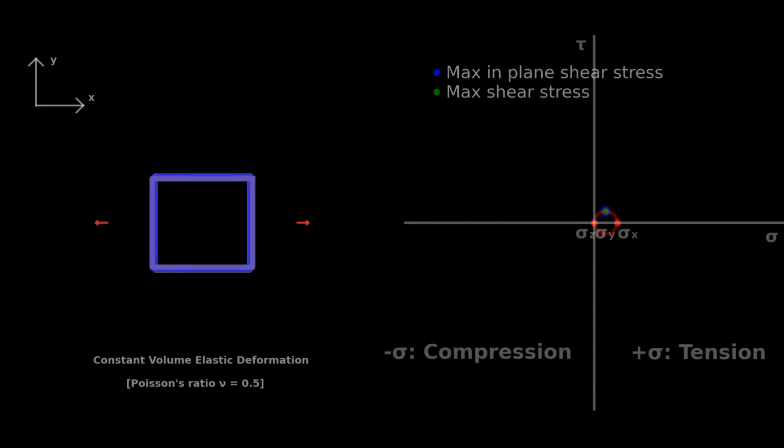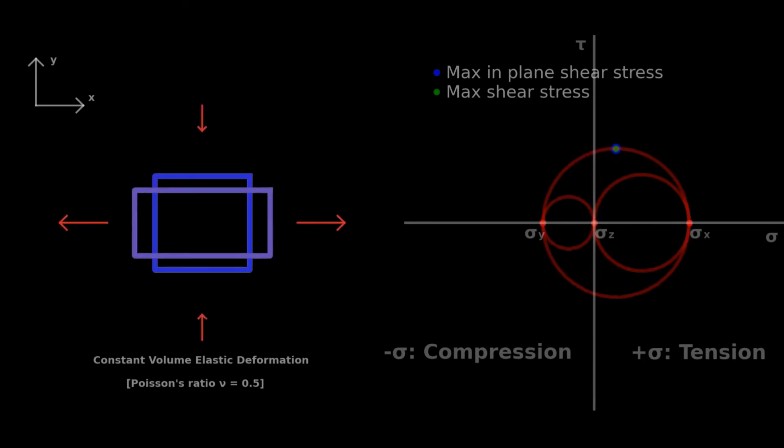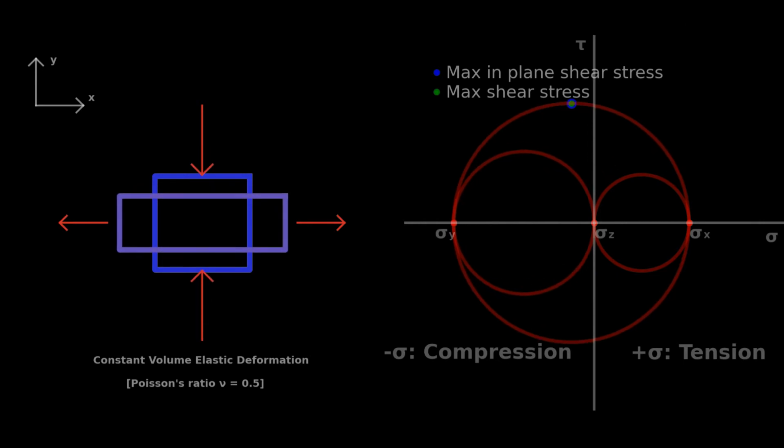In this case, we can see the Mohr circle if compressive stress is applied in the y-axis instead of tensile. Now the maximum shear stress is always in the xy plane. Based on all of the examples, it appears that the maximum in-plane shear stress is based on the difference between the normal stress applied in the two axes of that plane.